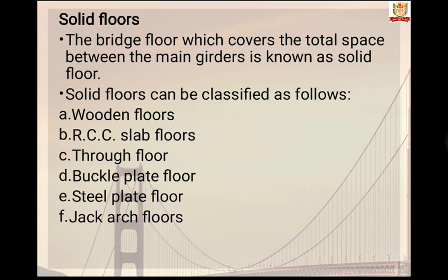Solid floors. Those bridge floors which cover the total space between the main girders are known as solid floors. Solid floors can be classified as follows: wooden floors, RCC slab floor, trough floor, buckle plate floor, steel plate floor, and jack arch floors.